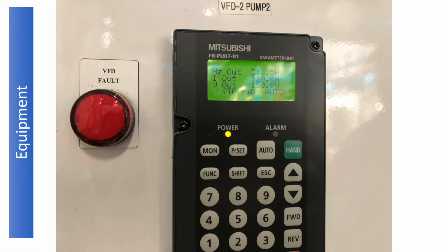What's really impactful about slowing down the speed of the pump is, if you remember from your engineering classes, the affinity laws, if you slow the speed of the pump, you save power to the cube. So there's a really great benefit in peeling off even like 10% speed off the pump. Sometimes we look to go to 90% speed, 85% speed, because then you're saving power to the cube by that simple speed reduction. So it's really quite impactful. And a variable frequency drive is how you accomplish that. So here's the tag on this one, VFD2, pump 2.